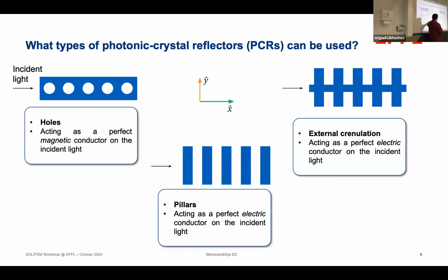And so this is a perfect magnetic conductor. In this case, it's the other way around, because if we come like this, let's say with a waveguide, this is the first unit cell, it means that there is a path here where you'll have the first void of low refractive index material. So you will have the maximum dielectric field in the pillar for the dielectric mode. That means that the electric field here is going to be 0. So this is a perfect electric conductor, because the electric field at the beginning of the mirror is 0.